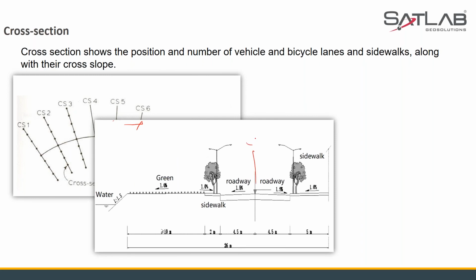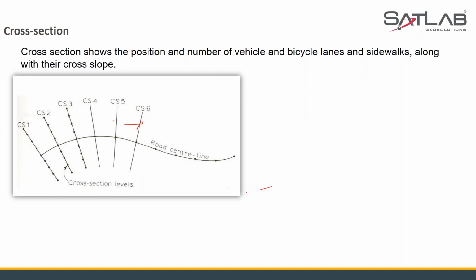Say for example, it's 10 meters, 20 meters, 30 meters. It depends. So I'm just going to delete it right now. There you go. So this is the typical cross-section of the road, in which I have a crown over here. This is my center point here, and then there's this roadway, or in some countries we call it carriageway. After the carriageway you can see the small curbs over here. The curbs are done. Then there's a sidewalk, a green area, then these side slopes over here.